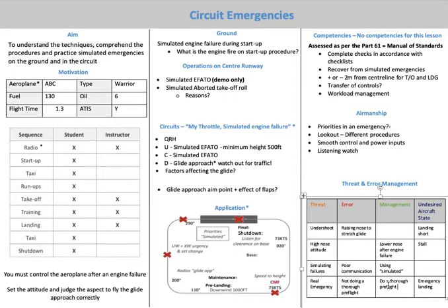On the runway, we'll look at the simulated engine failure after takeoff, demo only. I'll take off, cut the throttle. I won't actually cut the engine, I'll just simulate an engine failure. I'll lower the nose, land straight ahead, and apply braking as required to stop in a straight line. Remember, this is all in the quick reference handbook in terms of the takeoff safety brief, and you must do it on every flight, whether dual or solo, and from memory.